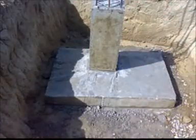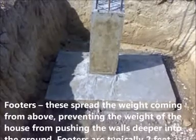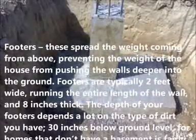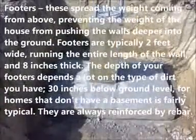Parts of a foundation. 1. Footers. These spread the weight coming from above, preventing the weight of the house from pushing the walls deeper into the ground. Footers are typically 2 feet wide, running the entire length of the wall, and 8 inches thick.